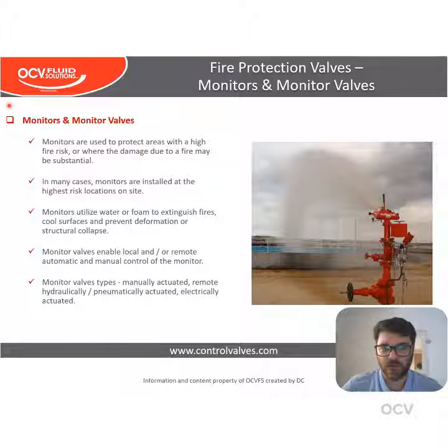So these are monitor valves. Okay, here we see a monitor connected to a Model 68 monitor valve. And monitors are usually used to protect the highest risk areas at your site where the fire damage can be substantial. Monitors can utilize water or foam to extinguish fire, cool surfaces, and prevent deformation or structural collapse. And our monitor valves are available with manual actuations, remote hydraulic and pneumatic actuations, and electrical actuations.